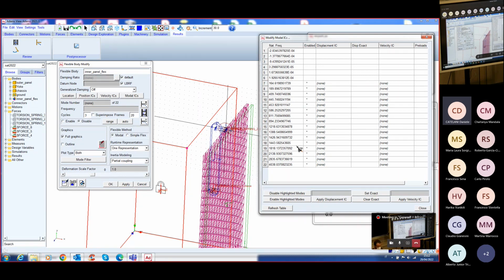So these modes can be manipulated and investigated after the analysis using the participation method or energy investigation method, and only after the analysis can you decide which modes are very important and which can be deactivated, not before the analysis.